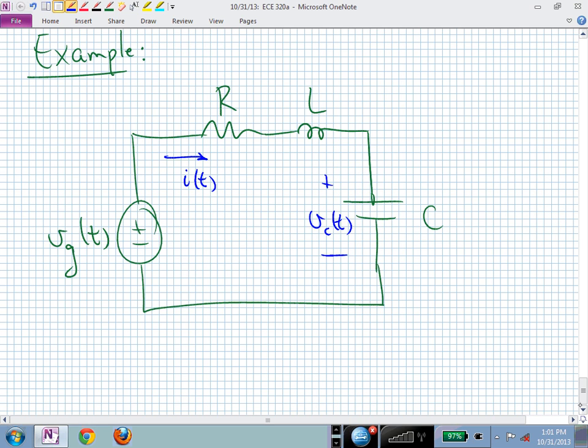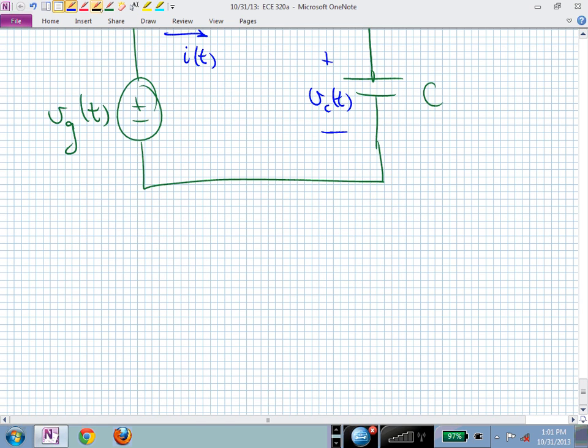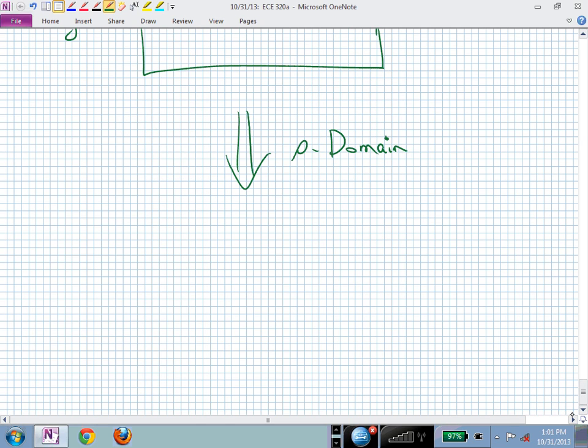Now, if we're interested in transfer functions, you're going to like this. When we push it down into the S domain equivalent circuit, if we're just interested in the transfer function, we can neglect the initial conditions. So now we don't have to do what I just lectured on 20 minutes ago. We simply replace the R's, the L's, and the C's with their impedances. We forget the initial condition pieces. And that's okay, because we're just trying to find the transfer function. We're not wanting to know the transient information or the information due to the initial conditions.